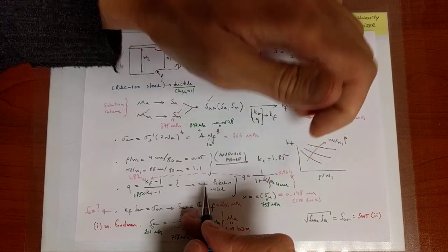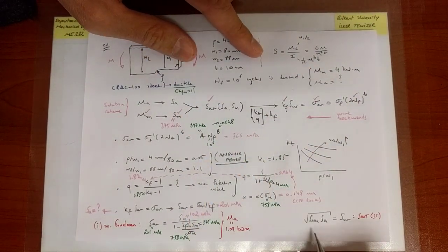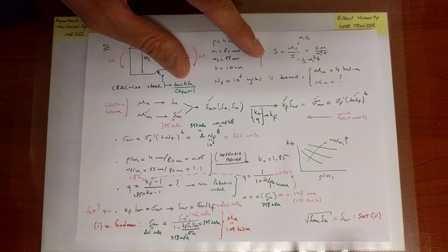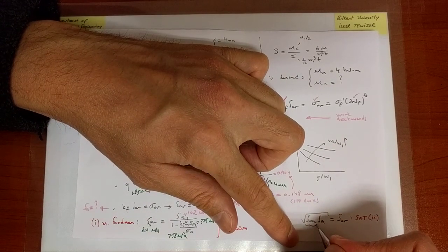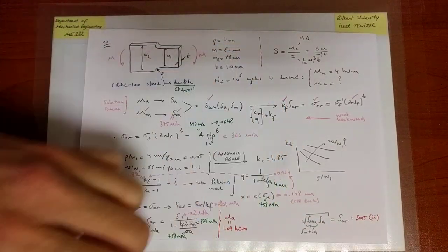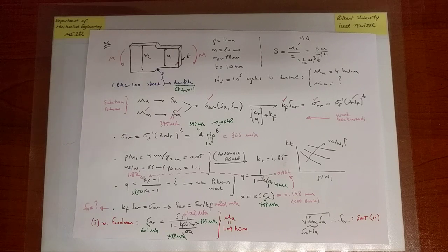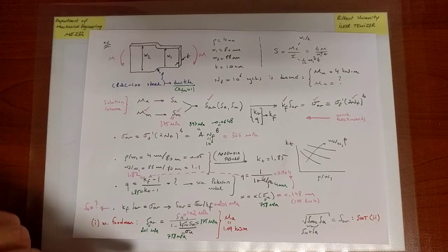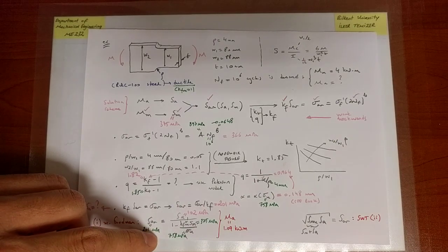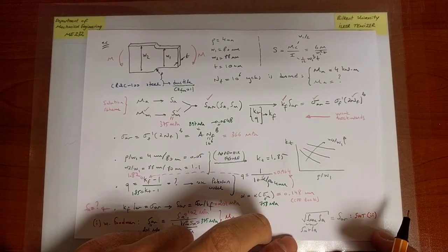It's still some function of SA and SM, and that's the form of the function for the Smith-Watson-Topper approach. And here S max is equal to SM plus SA. So now there is no material parameter here, unlike the modified Goodman, and in fact KFM does not even appear in there.